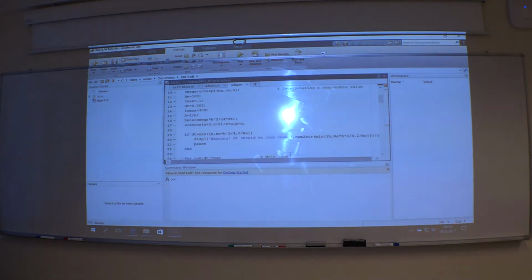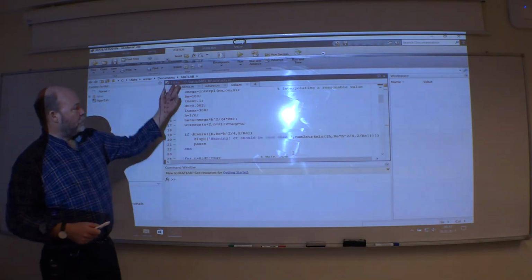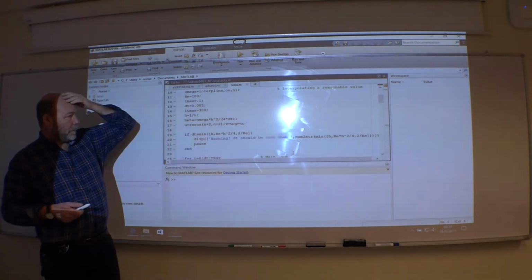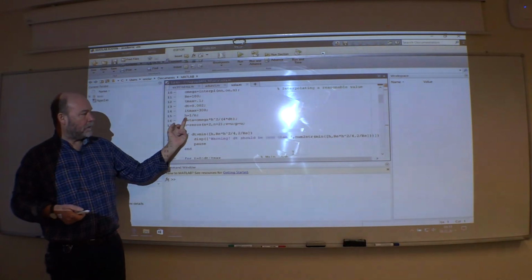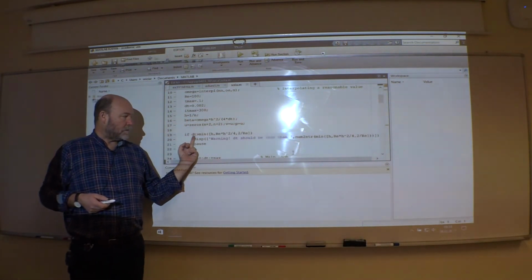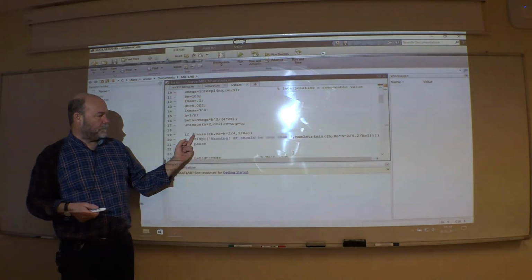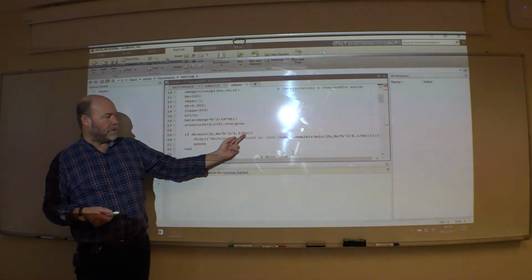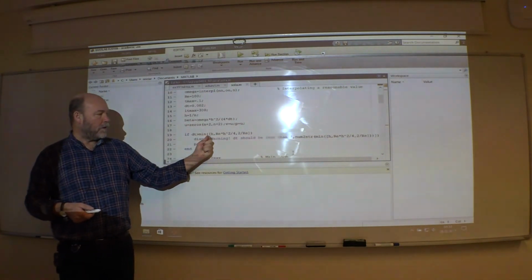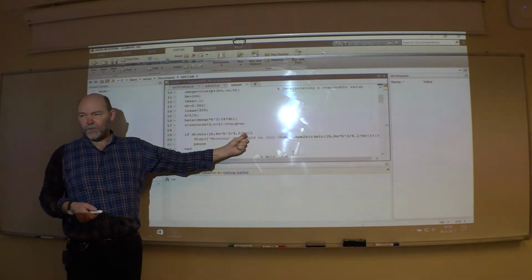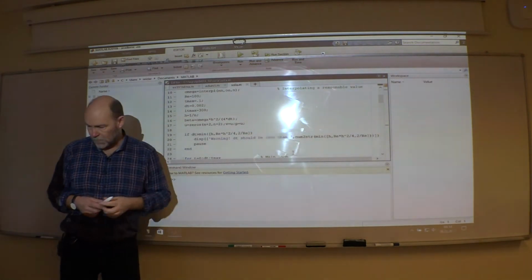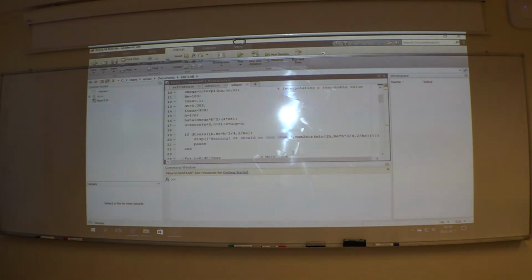Here's the beginning of the Strouhal code. You choose the time step, you choose the Reynolds number, and you choose how many cells you want, and you get the delta x and delta y equals h. Then you have an if sentence. Delta t, if it's bigger than the smallest of these three expressions, then you get a warning. Delta t should be smaller. So here you have the stability criteria, and we have three of them. Where do they come from? That is the task. Find them.